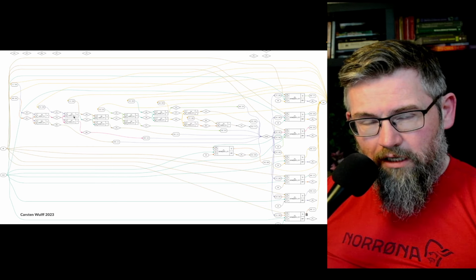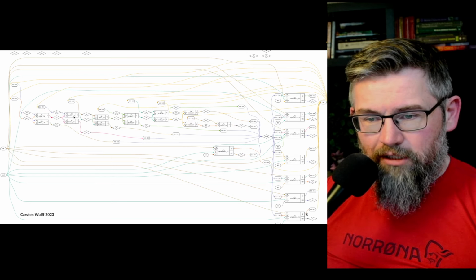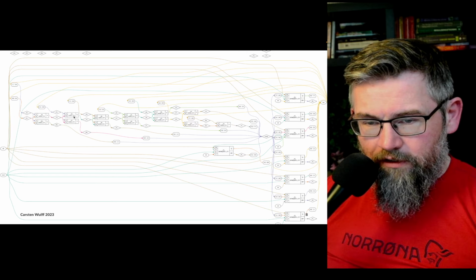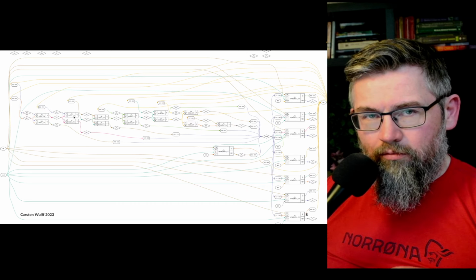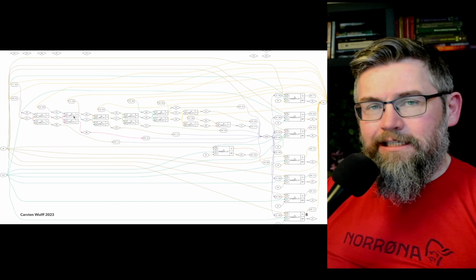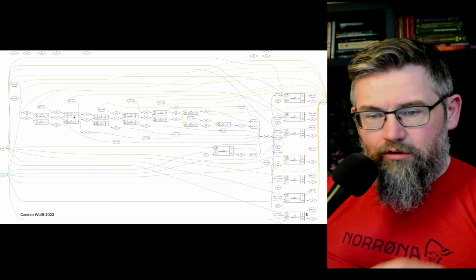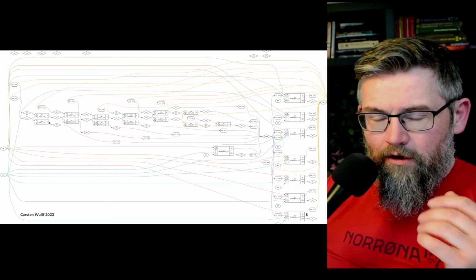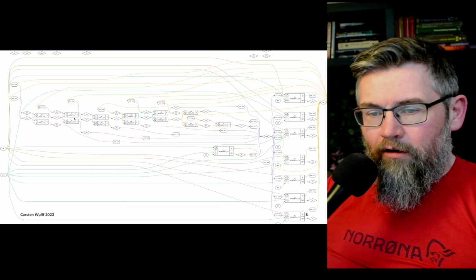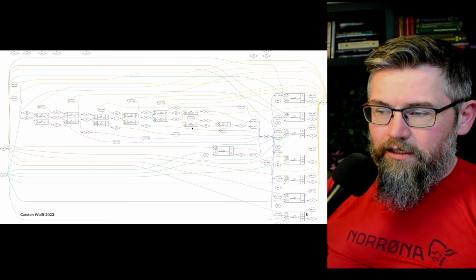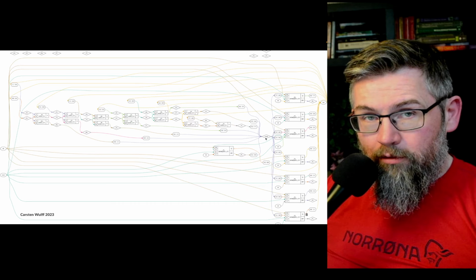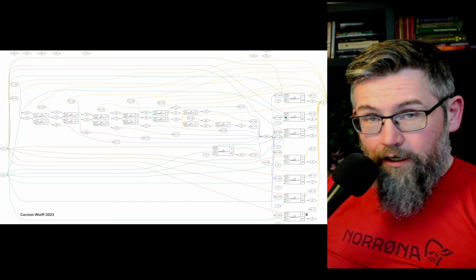But then you're getting into a situation where it could actually be quite a lot of stuff that changes, and there's a lot of components in there. So it's also possible to, in digital, run what's called a static timing analysis. Since you know all the delays, you can find the critical paths and you can prove that the delay of the full adder tree is short enough for the count variable to be correct before the next clock strikes.